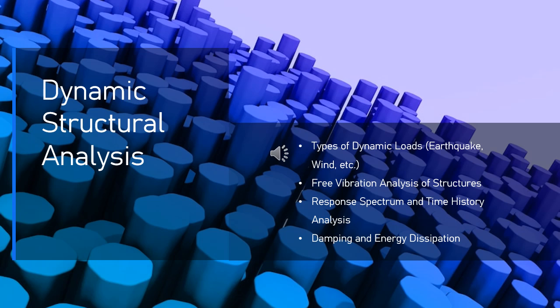9.5. Importance of damping in seismic design. Damping plays a crucial role in seismic design, where controlling the dynamic response of a building to an earthquake is critical for its safety. Structures with higher damping will have lower peak displacements and forces during an earthquake. Seismic damping techniques. Base isolation. In regions with high seismic activity, base isolation systems reduce the energy transferred from the ground to the structure. By isolating the building from the ground motion, these systems reduce the peak displacement and accelerations.